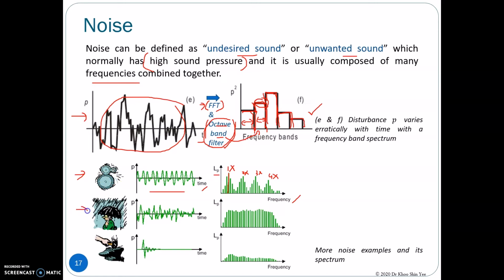When we take the sound measurement for running, in this case, we obtain more random data in the time domain. And after you convert the noise to the frequency domain, we obtain the sound pressure level in a broadband manner, where you see the magnitude of the pressure is almost constant over a broad range of frequencies.